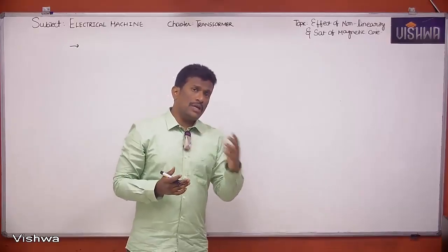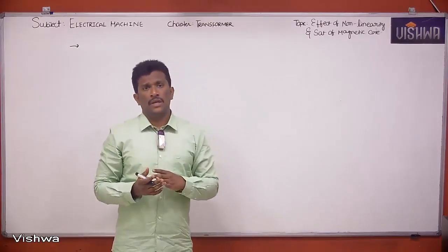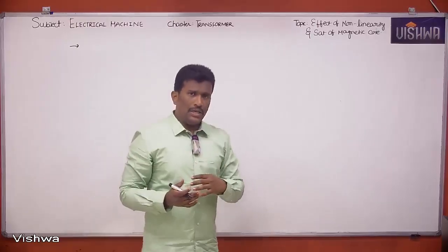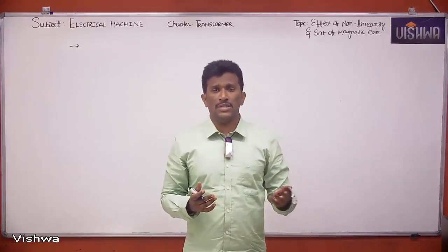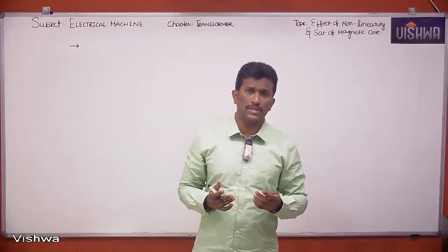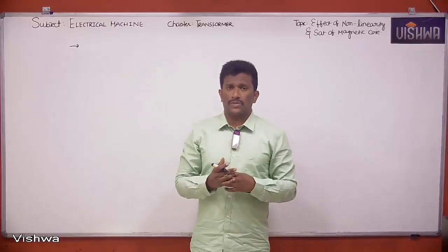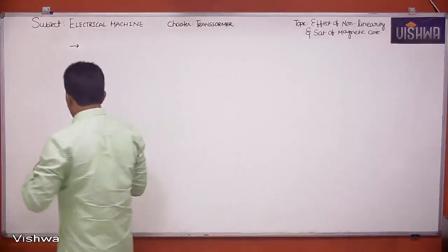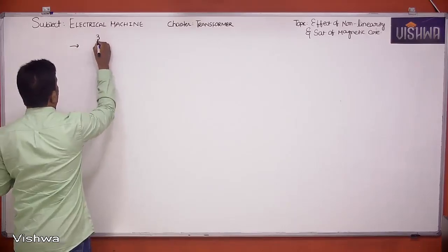So before deciding whether a path is there or not for third harmonic currents, let us see whether a path is there or not for fundamental currents, for negative sequence currents, for positive sequence currents. Then we'll see about your third harmonic currents also. Here you have to understand a small thing, so if you take a three-phase system,